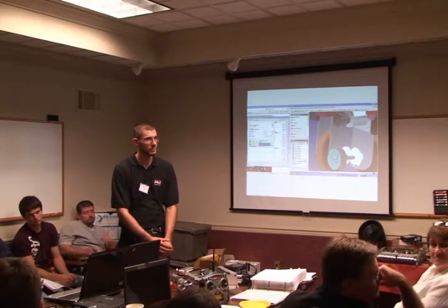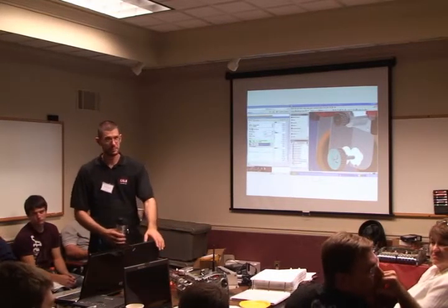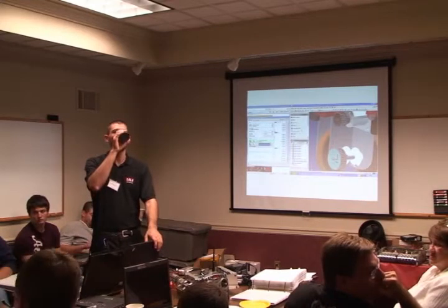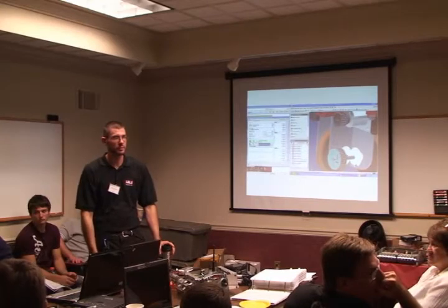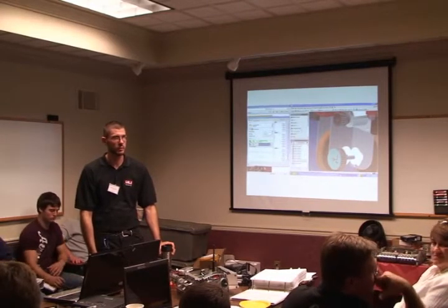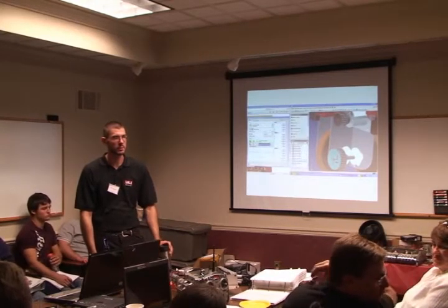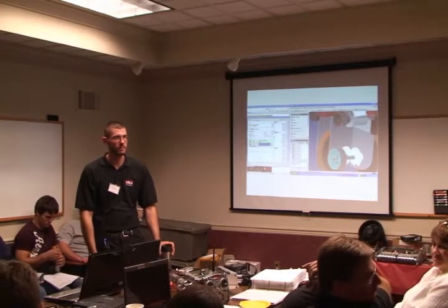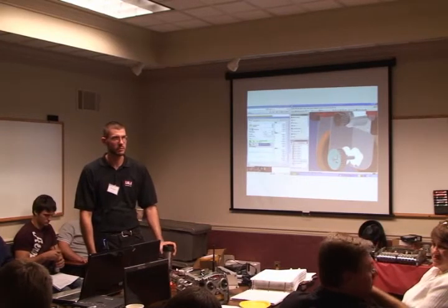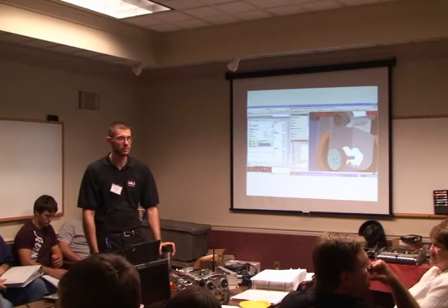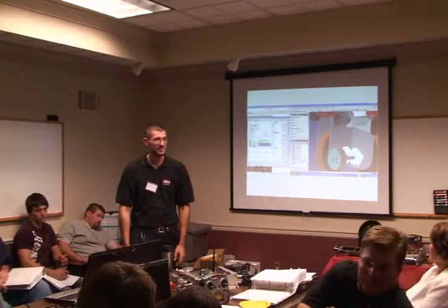Yeah. Another thing, when you order your belts, you need spare parts. Order all your belts, including your spares, at one time, because if you get them from a different order, they could come through maybe a quarter of an inch different in size. So if you have a robot that's going to take 2 belts, you want 2 spares, order 4 belts right from the get-go. McMaster-Carr is pretty good. If they're not the right size, they take returns quite easily. But don't order 2 now and say we'll get 2 later, because we ran into that and they were different in size, and then that messes you up, especially if you don't find out until a competition when you have to replace something. So try to order all your parts in one shot.